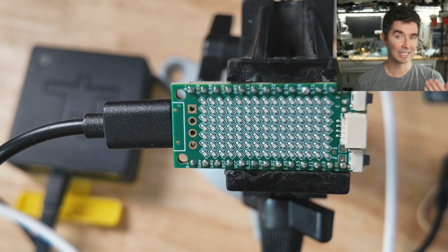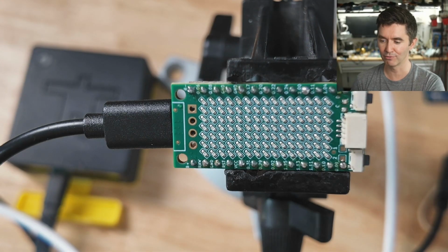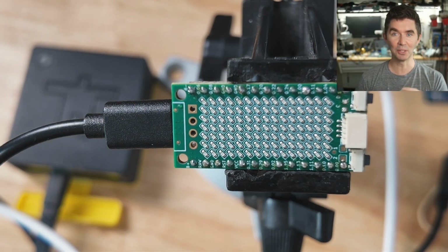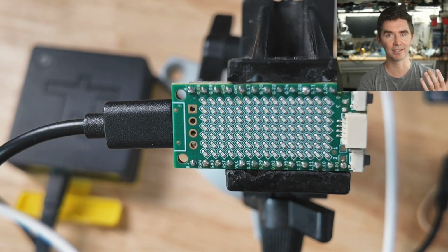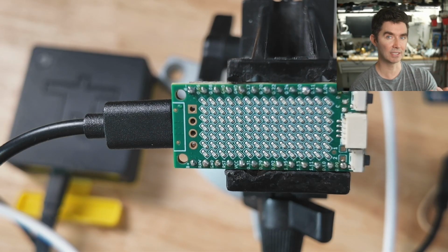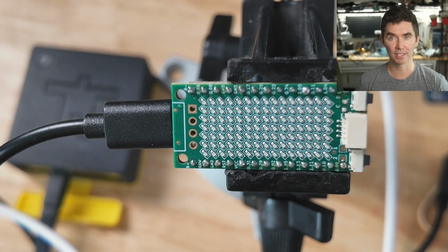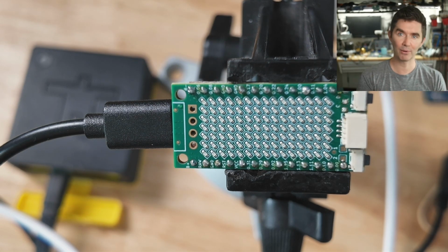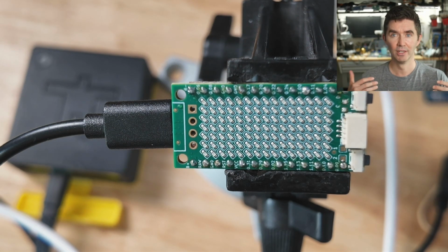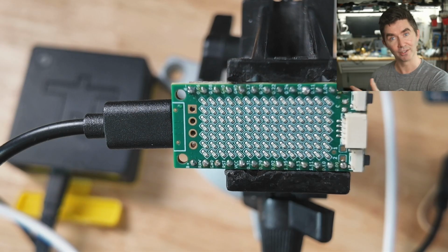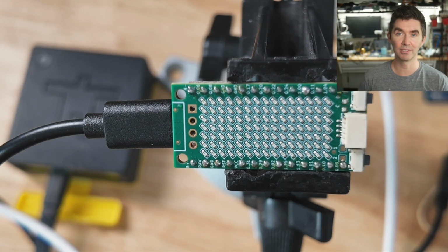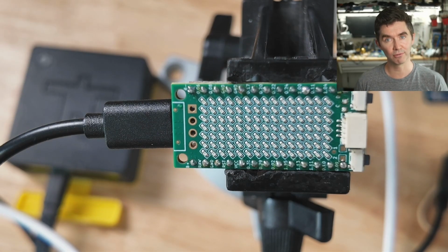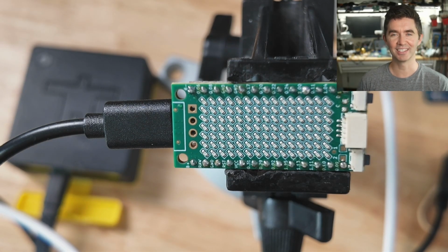We're going to be talking about this setup here, but what I really want to point out first is this right here, which is the USB cable, and really just the connected nature of most IoT devices at the beginning of a development process. Usually we're first talking to it over a programmer, but then usually we're powering it over USB, talking to it over USB, talking to the serial interface, talking to the shell through the serial interface, and this is just how a lot of IoT devices work. You're usually working on them locally first. And so that's where a lot of this local shell made a lot of sense.